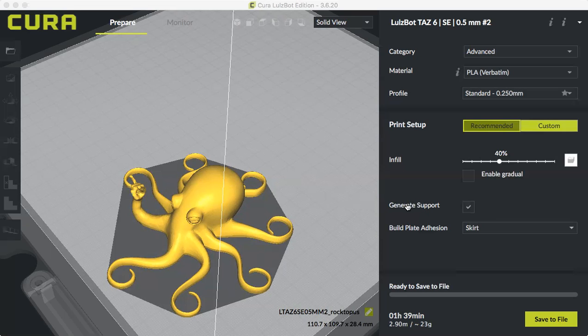Okay, the third option is brim. And so the brim doesn't go underneath the model. Actually, it's not underneath it. It's just like a hat. So it starts printing and connecting to the very outside of the part. And it just gives you a little bit more build plate adhesion. So if you've got a decent area that's touching the build plate, but you'd like a little bit more security to make sure it doesn't come unstuck, you would select the brim.